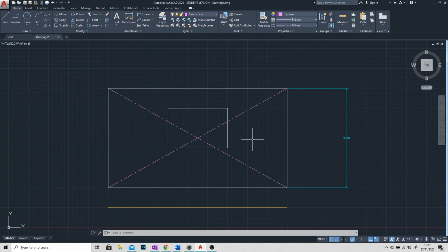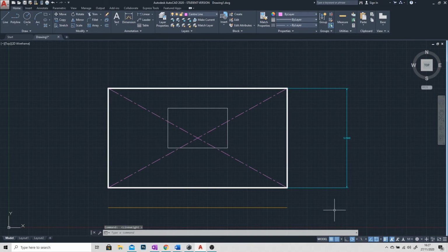To change the preview of Autocad, effectively to see the line weight as you're drawing, you need to go down to this little icon here, kind of 3 dashed lines with varying thicknesses. When you hover over it, it'll say show/hide line weight. Currently mine's set to off. And if I click on that, it turns it on, and now you can see the line weight changes.